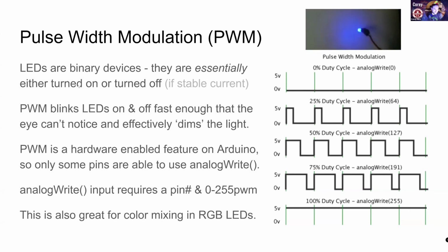So it turns out, Jamie, your question is, can you just lower the output to the pin instead of turning it on or off? And they're digital pins, so you can't. Some microcontrollers can, and Arduino articles sometimes are unclear. They say that analogWrite is analog writing a lower voltage, but you're really blinking it on and off faster than you can see, which is an important trick that gets used at all sorts of different levels.